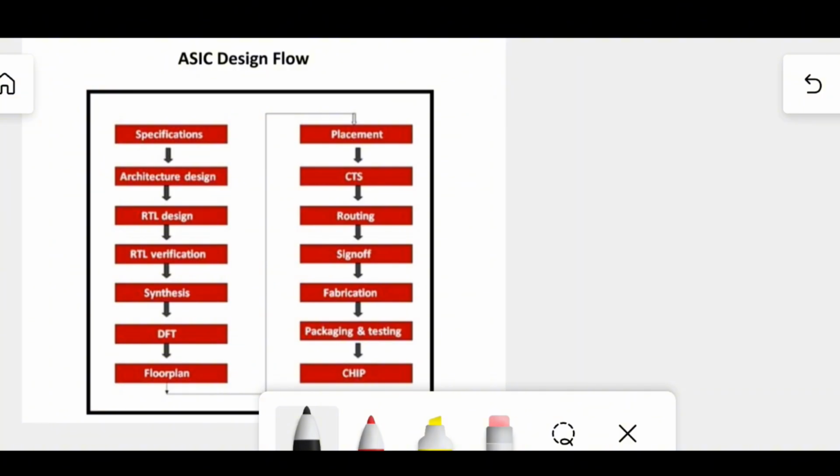Before going to the next stage, the connections between the macros, standard cells, clock and IO ports are logical connections. In the routing stage, we connect all the physical cells with metal. Routing is divided into two parts, global routing and detailed routing. In global routing, the metal layers used by the signals are decided. In detailed routing, the physical connections are made.